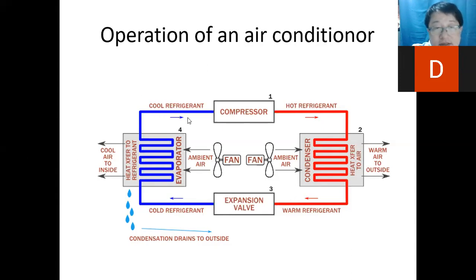Afterwards, this coolant will be compressed again. So the volume will be reduced, the pressure will increase, and the temperature will be high. And then this hot compressed coolant will flow through a fan, so that this high temperature compressed gas will cool down. In other words, the heat is taken away from indoor to outdoor. This is basically how an aircon operates.